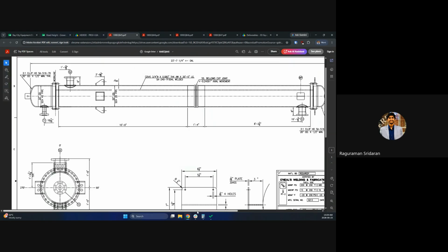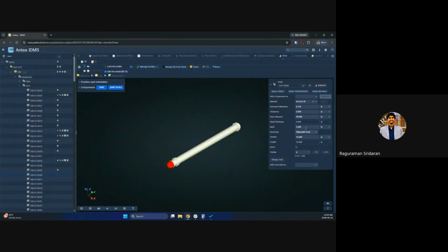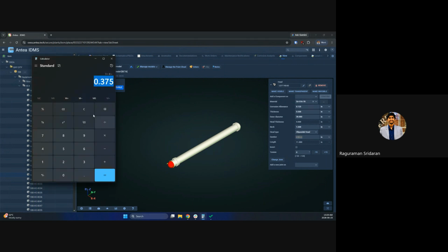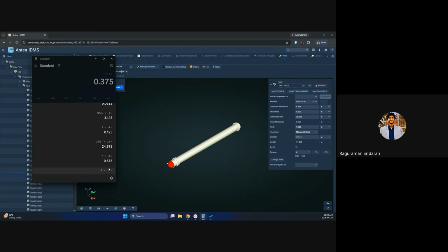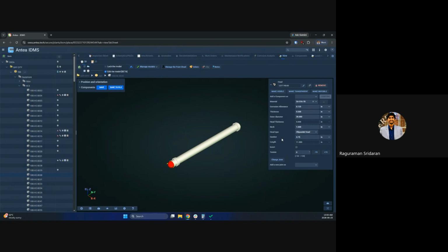Now we go with the straight face, the neck value. So for the 2:1 elliptical head, we just go with the value 1.5, straight face standard. And then for the height, it's going to be 4.75. See, it's 19 divided by 4, it's 4.75. Save.